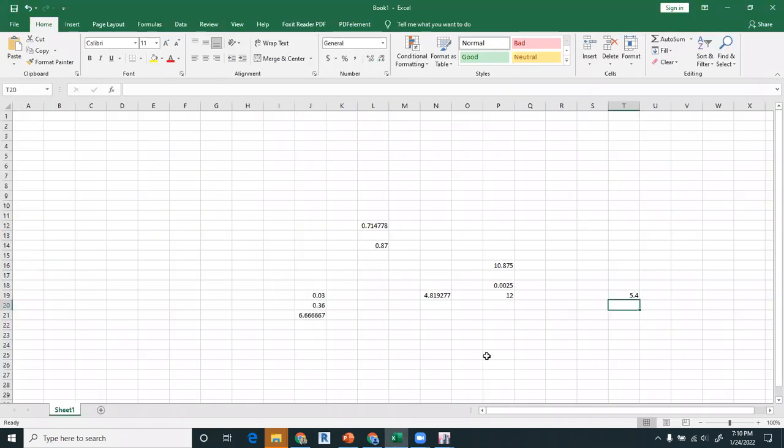So now let us do these calculations. So we have this, this is 20 inch square and we will divide it with 432. So we are getting 0.046 inch square per inch. If we use number 4 bars, so 0.2 divided by this, we are getting 4.32 inches, which is a very feasible spacing between these bars, because if you increase the bar size it will give you more spacing. If you use number 6 bar, it is giving you 9.5 inches. So whether you use number 4 bar at the rate of 4 inches or number 6 bar at the rate of 9 inches, this is your choice.